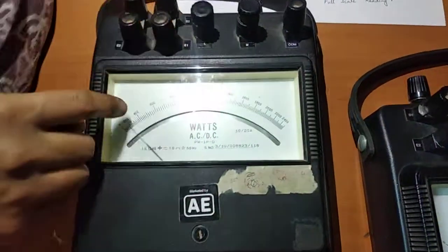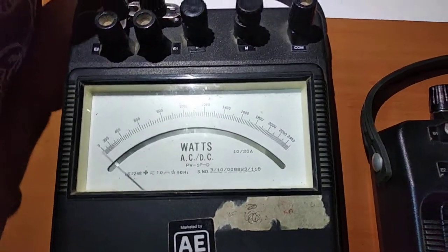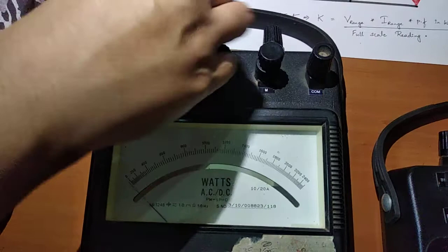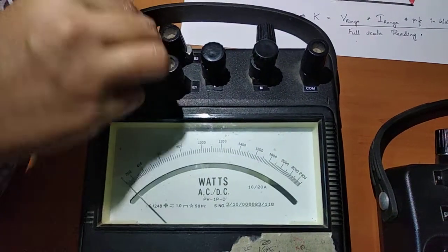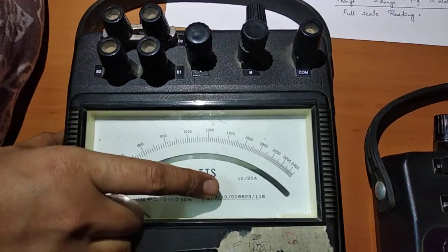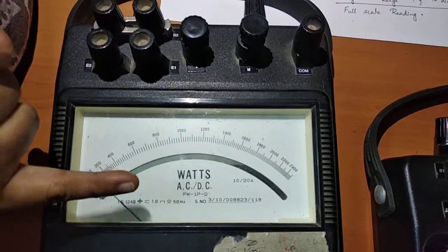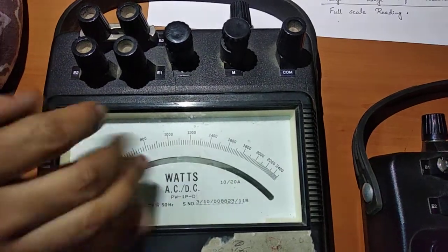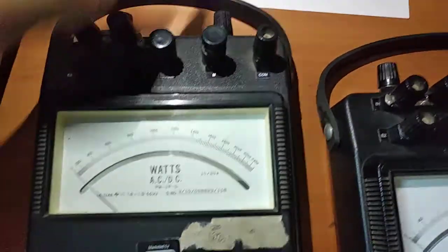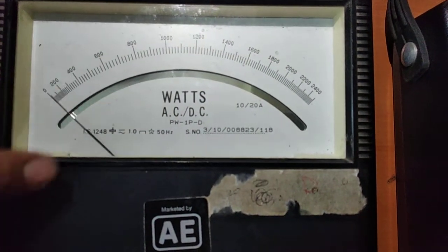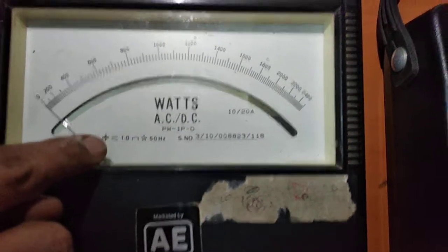And the current that we use in this particular case will be the lowest current because we need a lower current rating. So I am going to connect B1 and B2 in series so that the whole wattmeter is used to calibrate or use the I range as 10 amperes. So the voltage range is 500 volts and the current range is 10 amperes. And then power factor in the wattmeter. Please note that this is a wattmeter which is used for unity power factor. So that is given as 1 here.